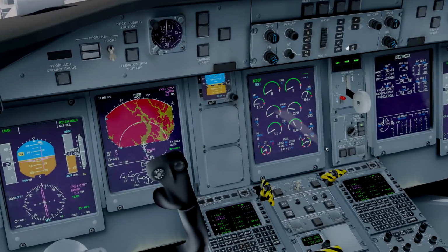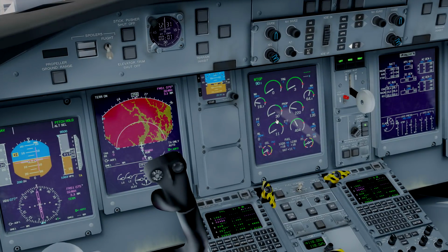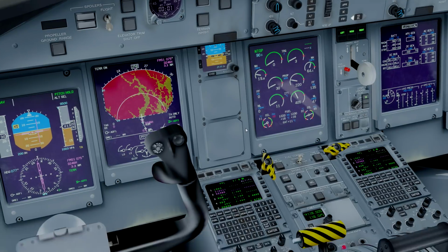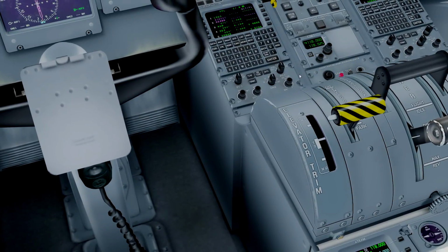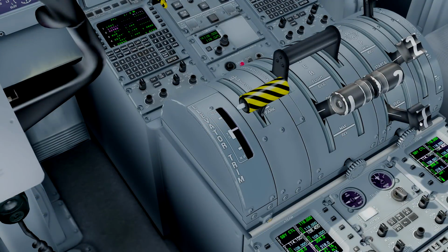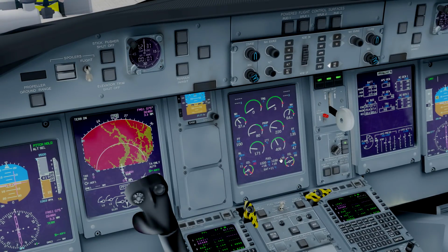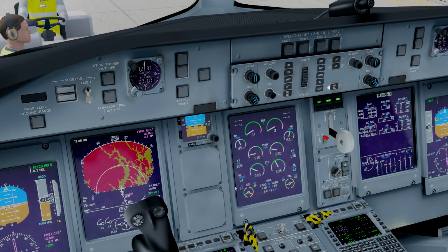Same procedure. Make sure to take a look at the different RPM indications. Meantime, we'll set the parking brakes for the ground crew. And then we'll put the condition lever to start and feather, which is going to introduce fuel into the engines again and let the engine start up. Oil pressure is rising, oil temperature is rising, and this engine will stabilize as well.